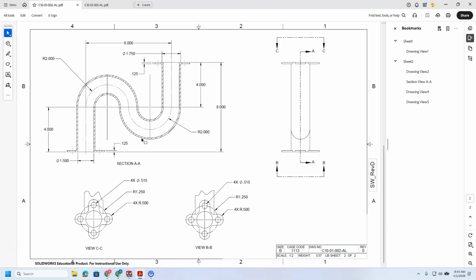However, with using the sweep command, circular profiles are so common that they actually added the option to automatically generate circular profiles for a sweep. So, all we need to draw is the center line that guides our feature, the path it's going to follow. Then we'll have to create these tabs on the end, but that's step 2.